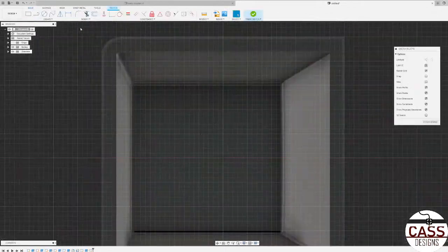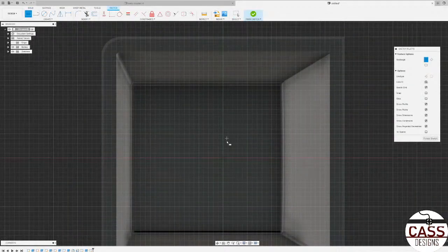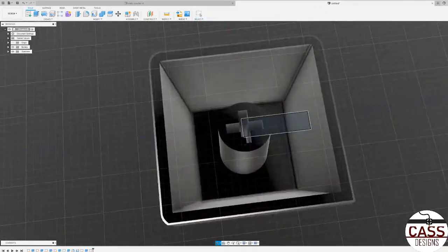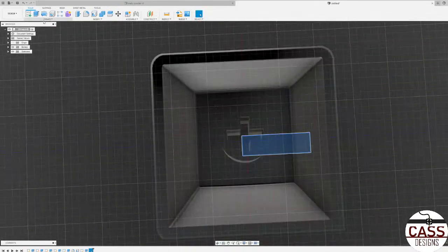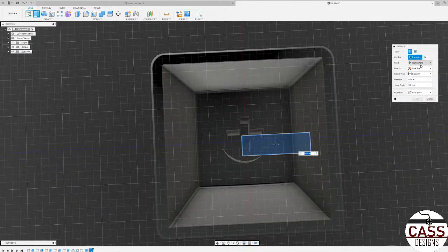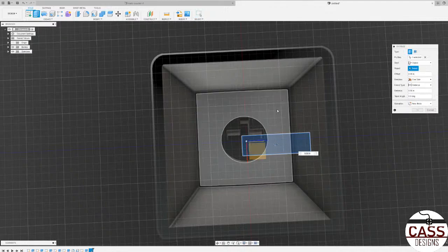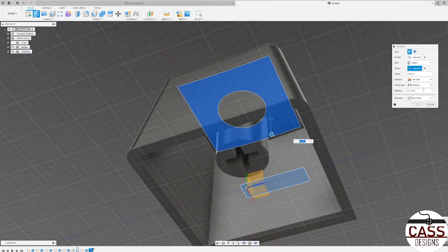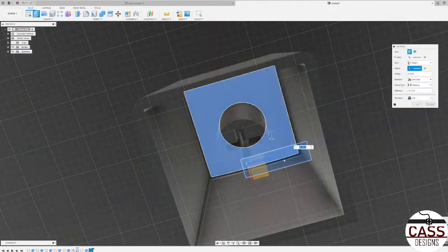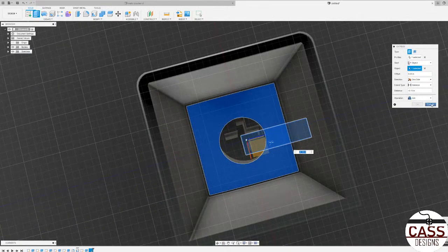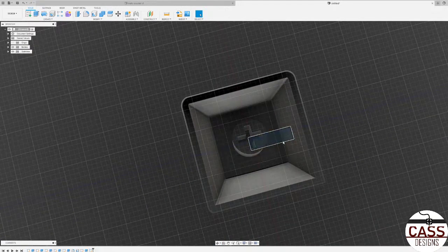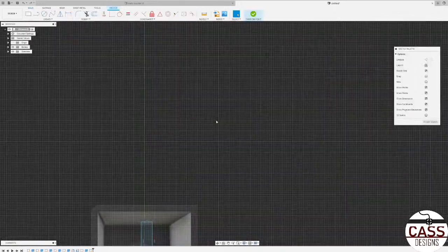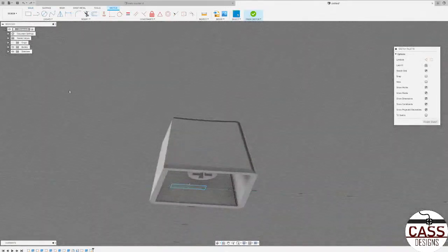So I'll click this. We'll go here. And say, I don't know, we'll do a little structural thing there. Finish sketch. It's not really in line, but it'll serve the purpose. So we're gonna click E. We're gonna click Start Object. Back here again. Extrude downward. Join. And it's not gonna do it. All right, we'll skip that right now. But that's something you can do to this. But this is just showing roughly how I created a keycap.